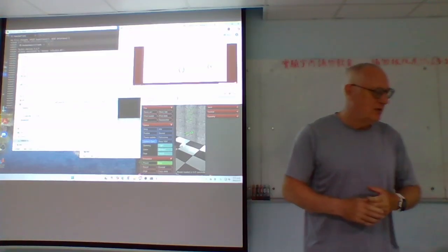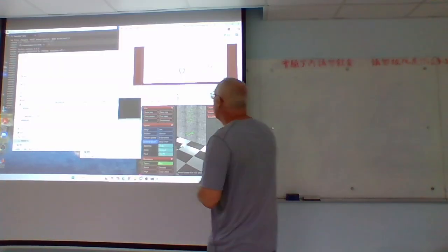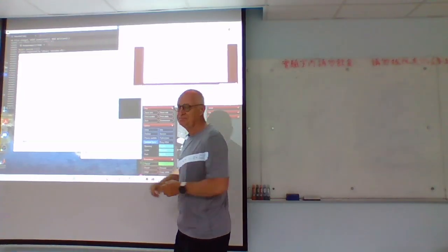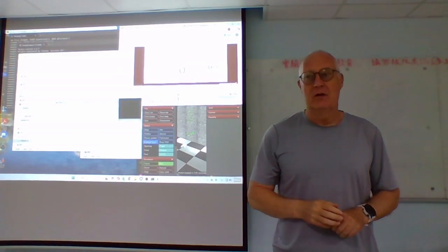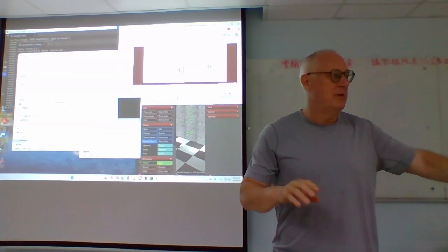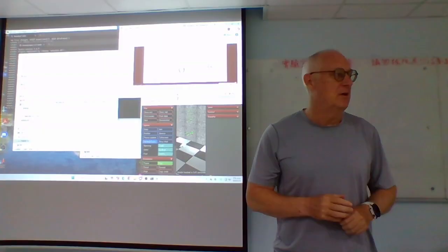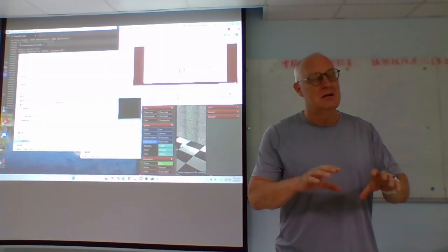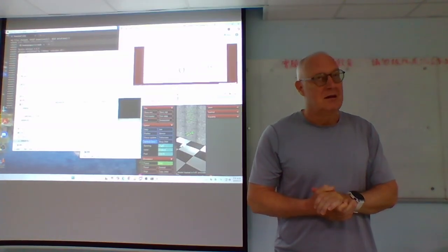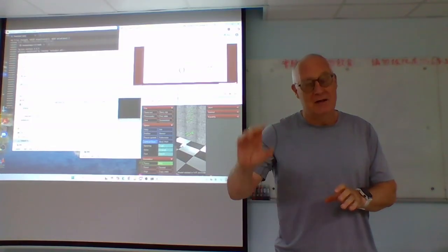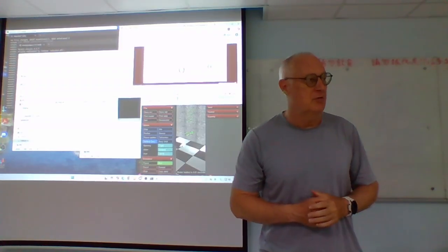Once we have these transformation matrices that go from one joint to the next, then we can calculate the compound transformation. Right? Because everything is a 4 by 4 matrix. If you left multiply them, you end up with the position of the end effector. If you multiply the points by the matrix and you keep left multiplying, then that's the transformation that you end up with.